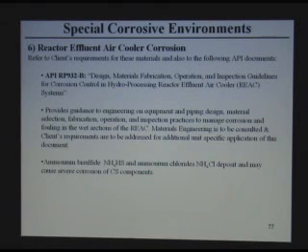Water injection is very critical in controlling this corrosion, and you have to ensure that the water you inject is equally distributed into the banks and the individual tubes. So this is the background of it. You can use carbon steel if the conditions are not so severe. Otherwise, many people now use Incoloy 825, or some people use duplex stainless steel.